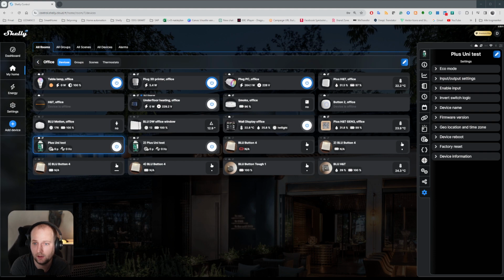I have a lot of light bulbs here less than 10 watt, and it works perfectly because I have a neutral connected. There are some advertisements that if you have less than 10 watt, you would need the bypass, but not if you have a good quality light bulb. If you have a dimmer without neutral connected, you will need at least 10 watt or the bypass.